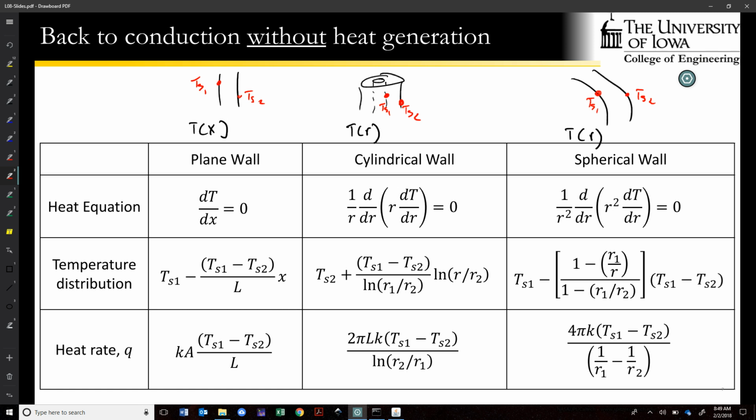The other thing that's nice about this is that basically all of the terms in this heat rate have something that reflects the difference in temperatures between the inside and outside. It's basically some constant times that temperature jump. So this leads us to what's going to be the main takeaway from today, which is now known as the resistance analogy.